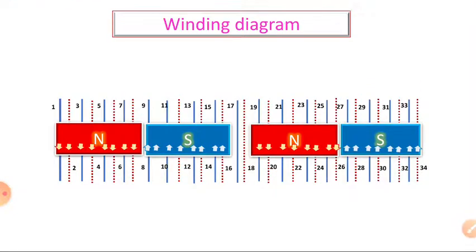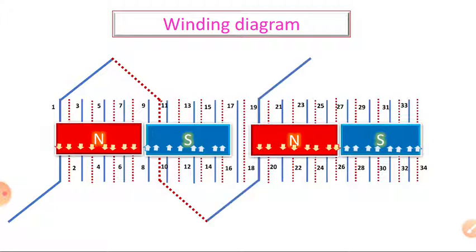Okay. Now connect all of these. Let us do the winding diagram. I am going to connect the first conductor, and what is the pole pitch? I have to connect the 10th conductor. So I connected the 10th conductor. Okay. From 10, I am going to connect to the 19th. So you are going to the 19th, top conductor, and next the other is connected to the other coil, the second coil. The other side of the other coil is connected to the bottom of the slot.